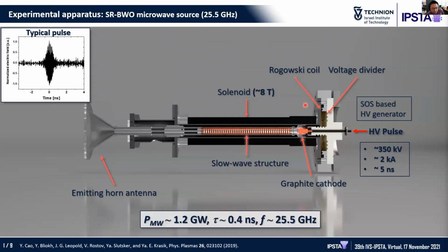Okay, so this is actually from the generation of this microwave. Our electron beam, with a certain velocity defined by our high power, high voltage pulse, propagates in this slow wave structure. So the frequency of this microwave is actually defined by the interaction of the beam with this slow wave structure curvature, which has the boundary over here.